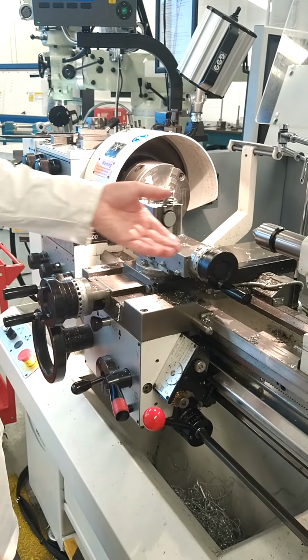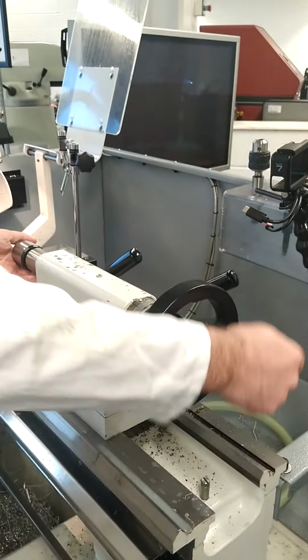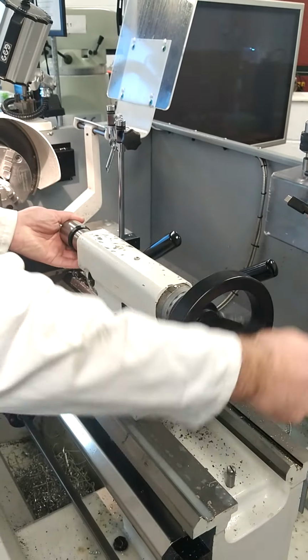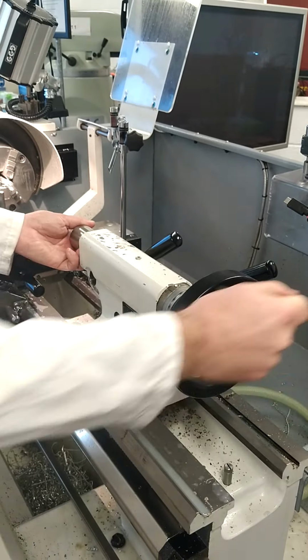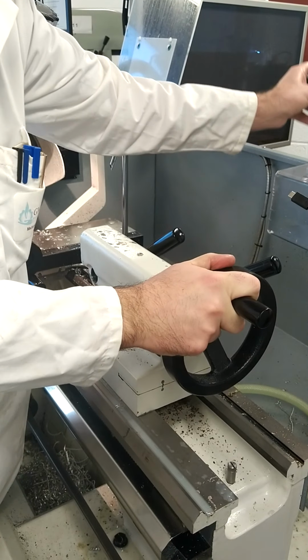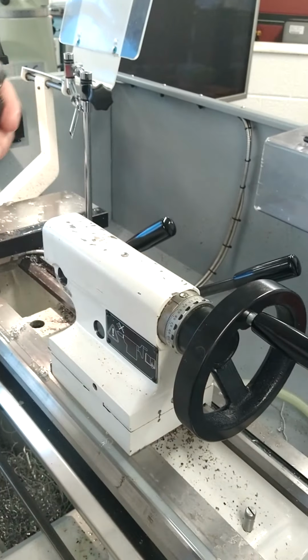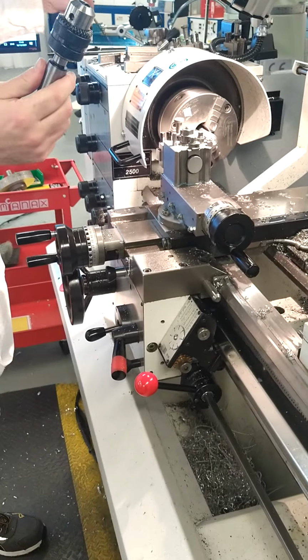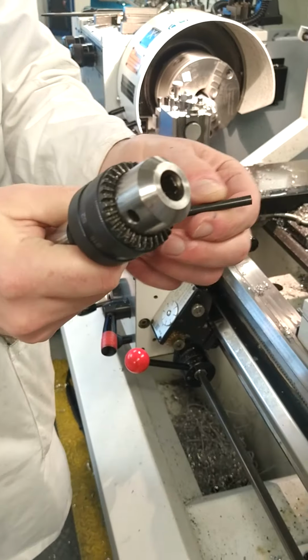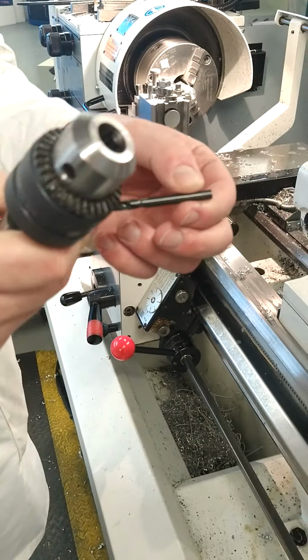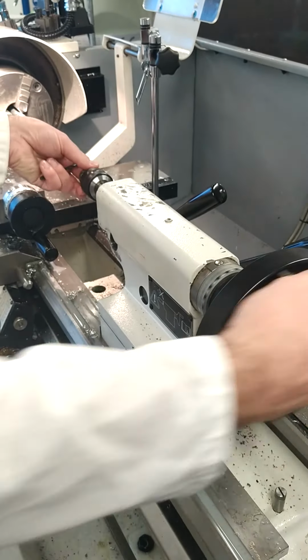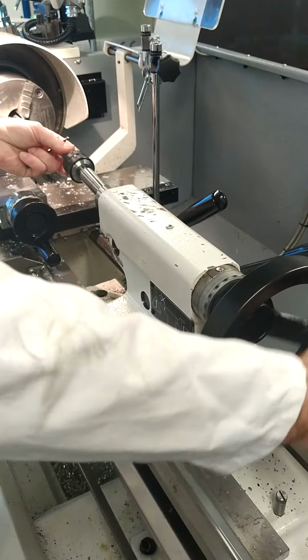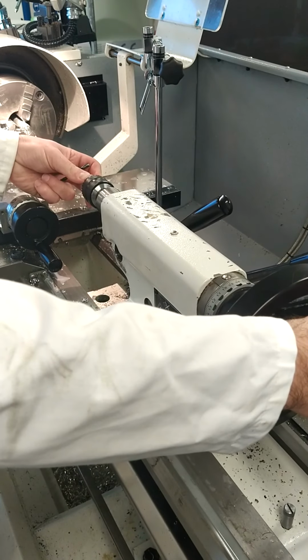Now for drilling purposes, we want to move out your revolving center. You've got a range of tools here in your chuck. This is a Morse tapered chuck, used for holding drill bits with a straight, parallel shank, up to size diameter 13, which can be put into this normal chuck. To put a chuck in, it's the same way. You need to wind forward to slot it in, 50-60 millimeters, and then it just clicks into place.